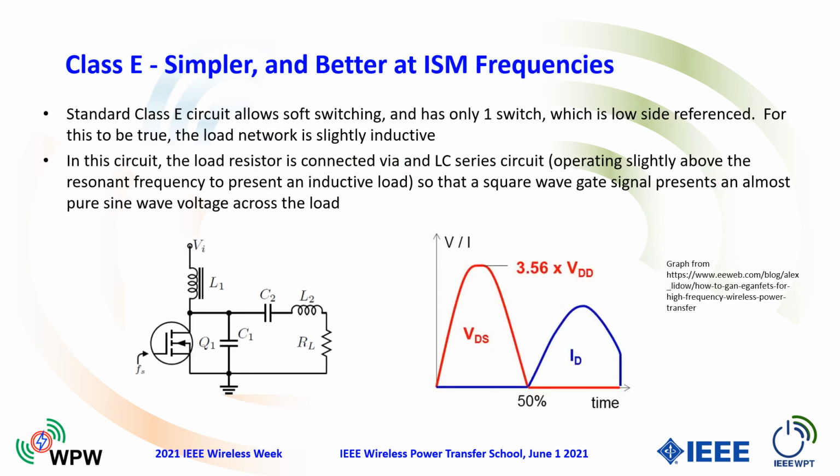So what is the solution that we therefore tend to employ at megahertz? Well, it is these simpler topologies, or perhaps they might look more complicated to you because they might be topologies that you're not familiar with. This is a Class E topology. It's an inverter. It produces from Vin here, which is a DC voltage, an AC voltage across the primary coil L2, and therefore an AC current in L2.